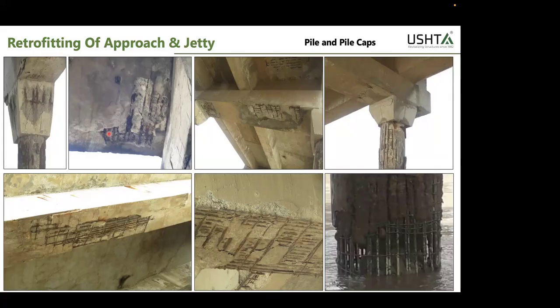Corrosion is basically an electrochemical reaction. So we measure corrosion by passing current. The higher the flow of current, the more the potential or the probability of corrosion, I would say. In this case, the corrosion was already there, and they were treating the bar partially. Earlier it was a 50-50 reaction. Now you treat almost 80% of the exposed reinforcement, and the unexposed reinforcement inside is not treated. So now it is like a 4:1 ratio. Your reaction will multiply, it will not reduce, and that would actually spoil the repaired portion as well.